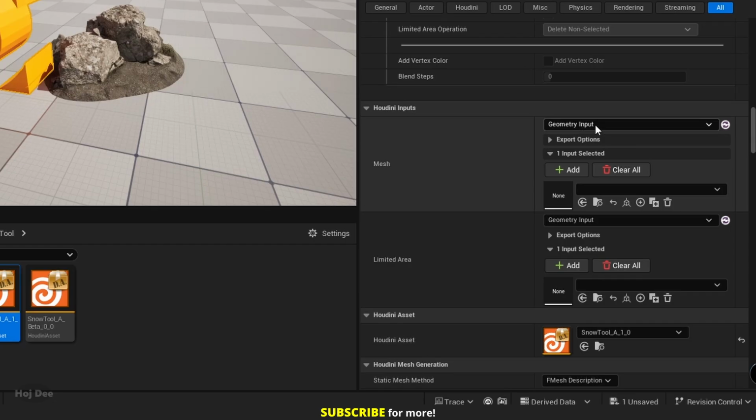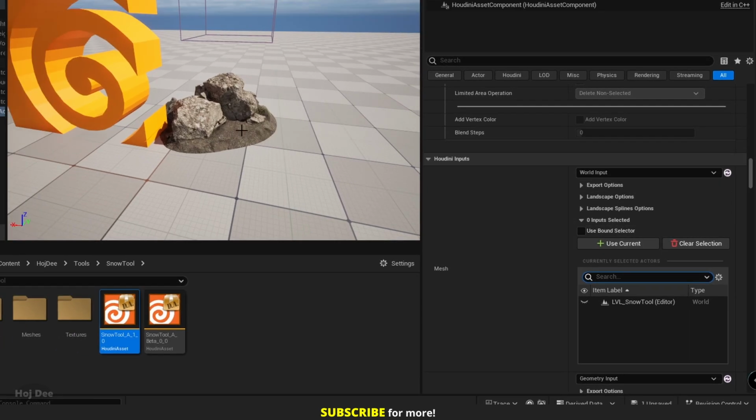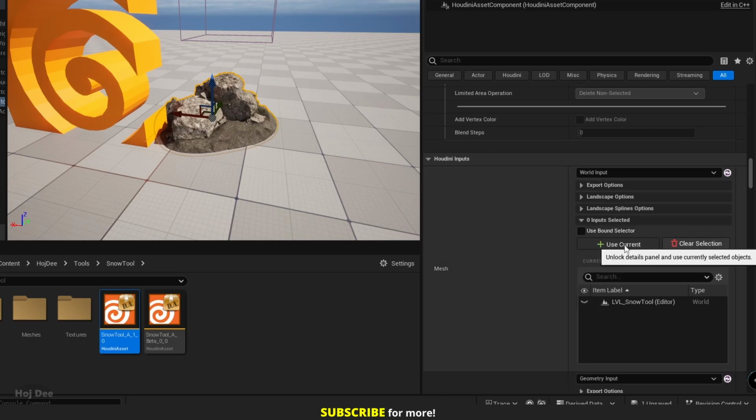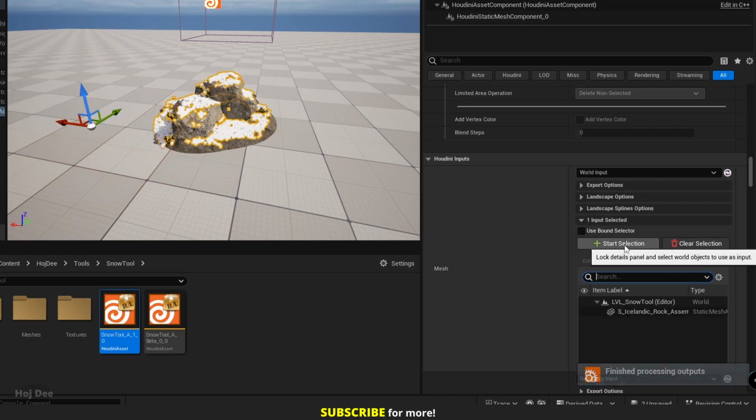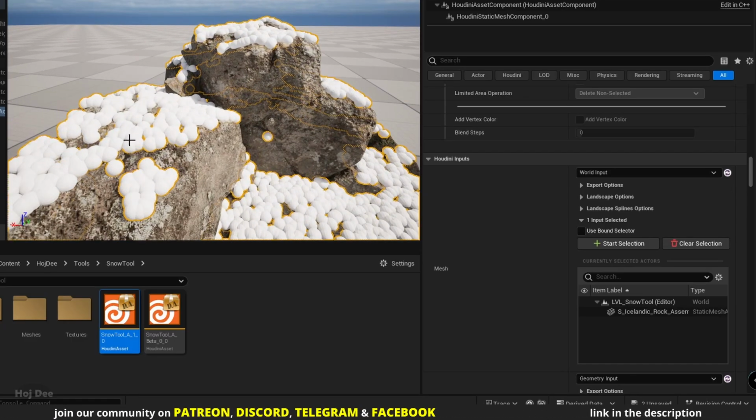So here click on geometry input and set it to world input. This way we can select the assets in the level. Down here click on start selection, and now we can select the objects we want to add a snow on top of from the viewport. We can select as many meshes as we want to add a snow on. So let's select this asset and click on use current. It starts processing and here it is. We can see that these spheres are added on the mesh.